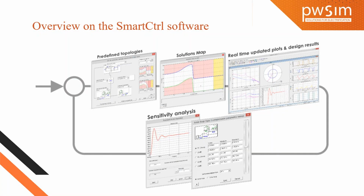In the frequency response, the noise which is always present in the system will result in poor performance. So we have to restrict that by giving the proper phase margin and gain margin. Coming to the Nyquist stability, it enables one to investigate both the absolute and relative stabilities of linear closed loop systems from knowledge of their open loop frequency response characteristics. These are all methods we have to take care of in order to understand well.